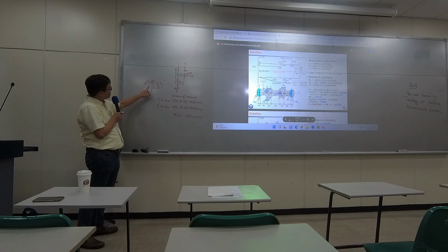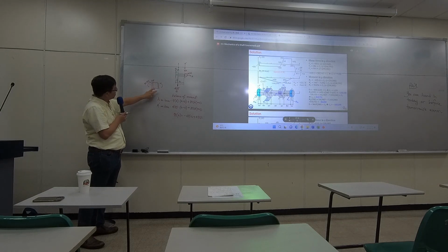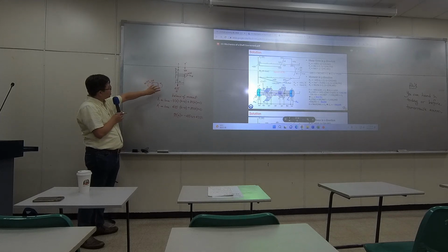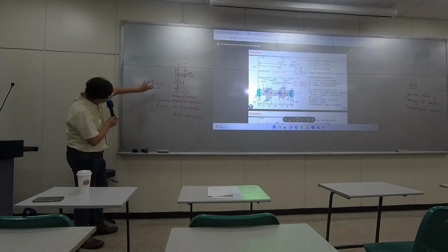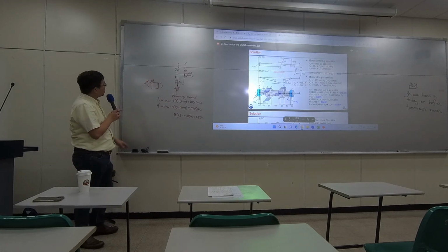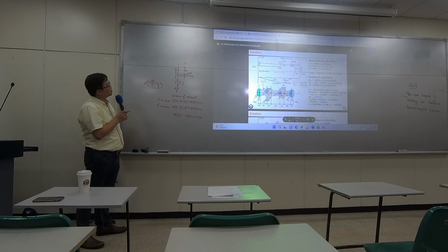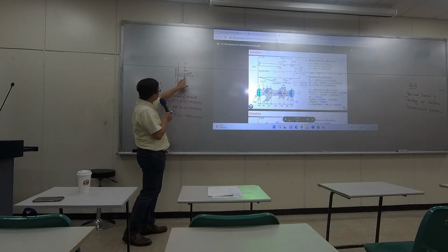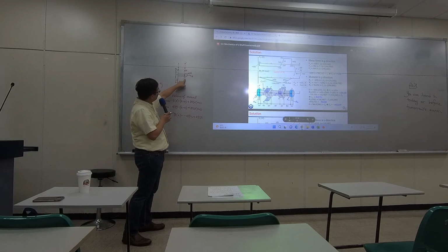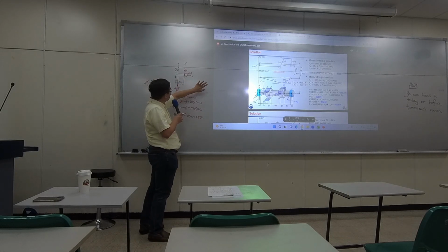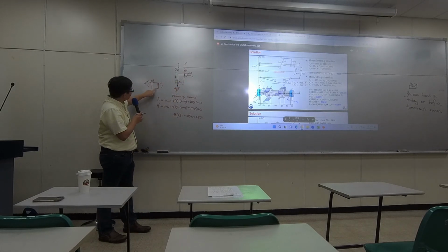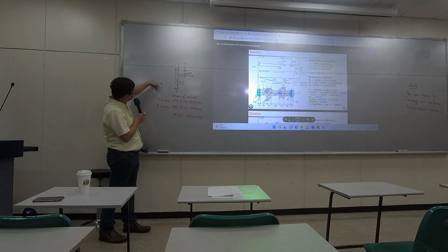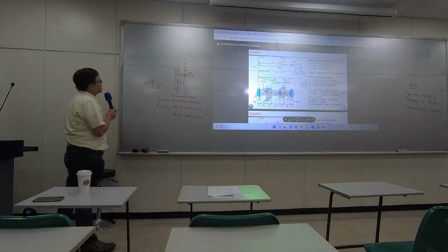So on the opposite direction, as a couple, the shearing force goes down and your moment makes a counterclockwise rotation like this, but basically the same amount. Since in this drawing we are observing the external force coming from the right, we are basically drawing this guy going down, shearing down, and then bending up from the right.